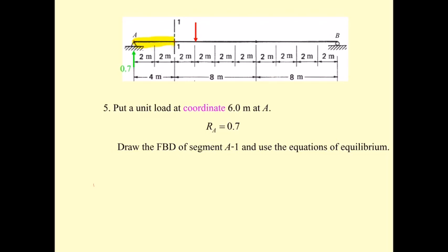Okay, and when the force stays on the other side of the beam segment and you use this portion, you can compute easier because the 1.0 unit will not appear in our equation. Okay, and if you get that, we just cut this portion and draw the free body diagram, and the moment and shear like this.